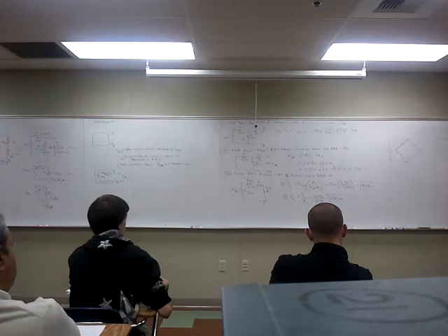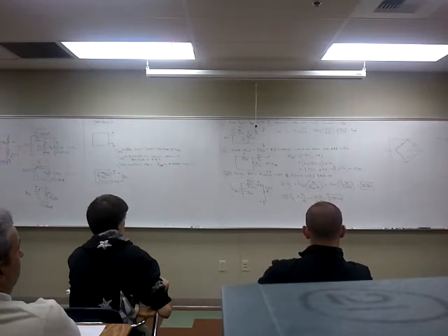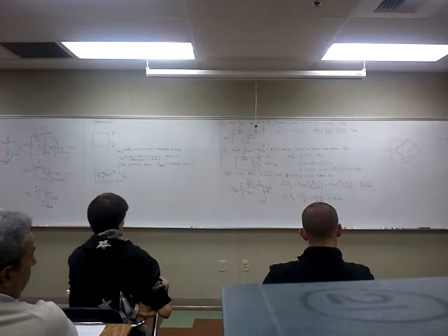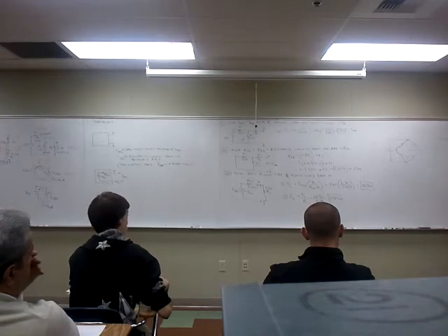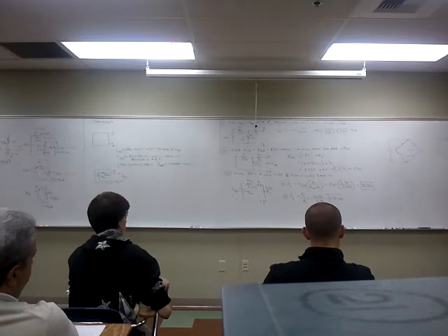V over R, you got an I. From the point of view of this supply, does it see anything over there? No, it's shorted. So what current flows here? V divided by R to get I here. So V over R to get I here, V over R to get I here. You got 2 I's. 1 I that this makes, 1 I that this makes. What do you think you do with those? Add them, exactly. Algebraically, you now know the short circuit current. That's going to be what's called the Norton generator.